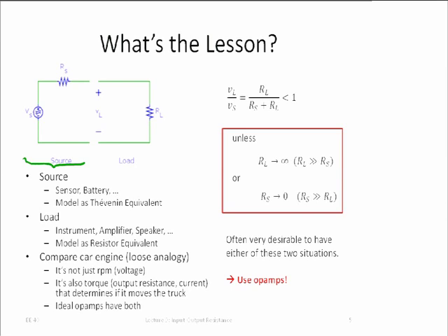And then we have a load here, and again that could be our operational amplifier. The load was 1 k ohm for the resistors that we had chosen, and in some other cases we use a DVM or whatnot, and then the resistance can be much larger. So in general, what we really measure is the voltage VL. What we actually want to measure is the voltage VS, right? We are not really interested in VL, that just happens to be a function of all these resistors. That can be whatever they want to be, but what we are interested in is what is VS, right? That's really the question that we are trying to answer.